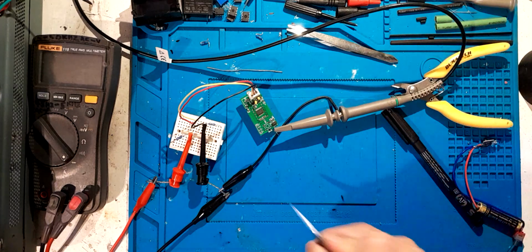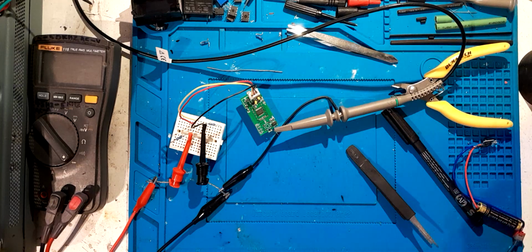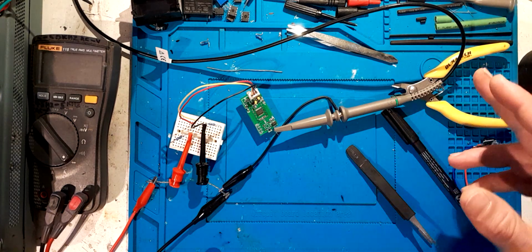I then changed R1 and R2 on the divider to precision resistors and then trimmed them with even more resistors, and I got it even more accurate from 0 to 30 volts, but now it's not perfectly accurate anywhere. So when it's turned all the way down, I think it's 1 millivolt out, and when it's turned all the way up, it's 2 millivolts out.